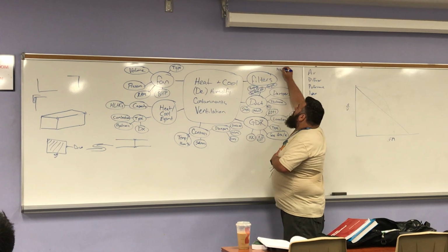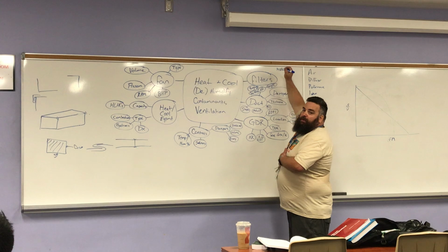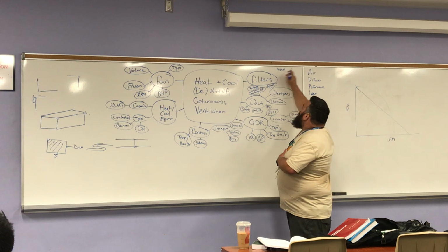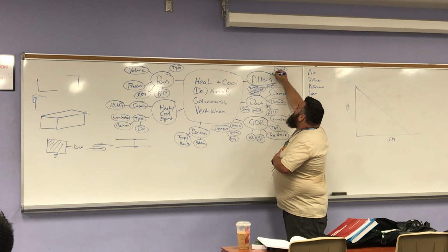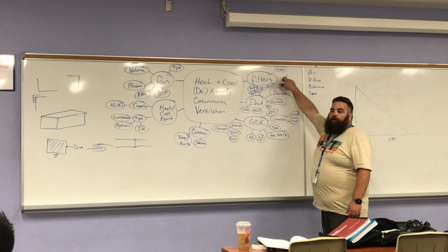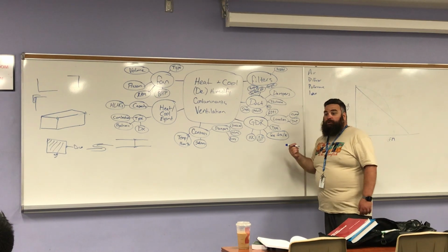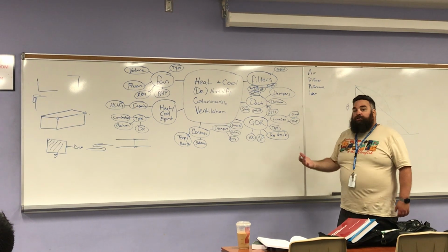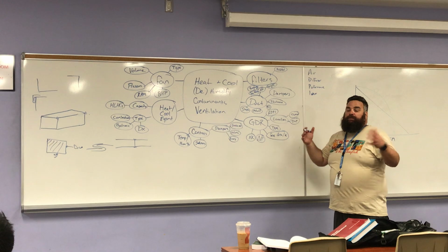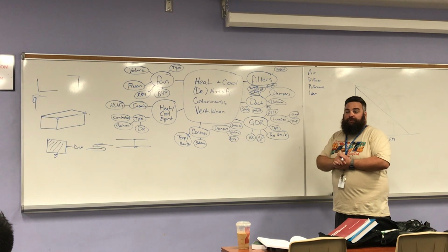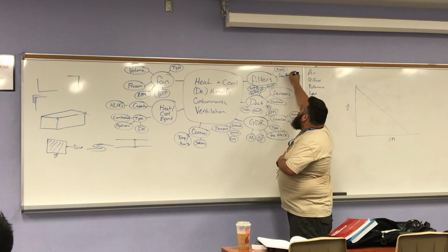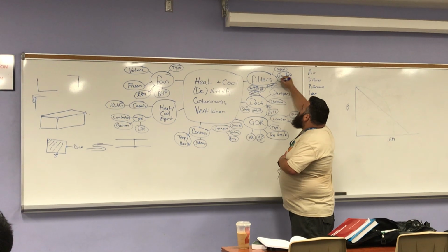MERV rating. You guys heard me talk about that. Minimum efficiency... it's too early in the morning for me to remember what that stands for. But that's the efficiency or effectiveness of capturing particle size. Okay? The higher the MERV rating, the finer the particles we capture, but also the higher the pressure drop. To counter the pressure drop, we can increase the free area. We can slow the air down because we've given it more free area. And that's what pleats in filters do, okay? So we'll have, again, free area, and we're concerned as well with leakage.